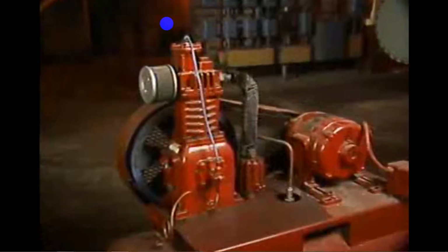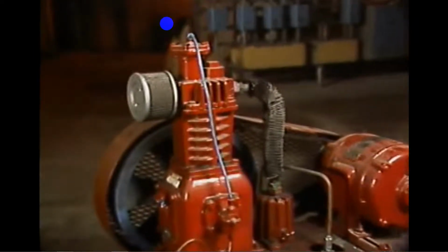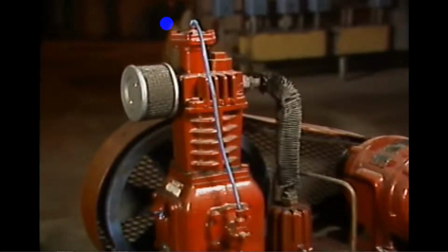Second, gases expand when they're heated, and since a compressor is designed to compress gases, this effect creates an additional force that the compressor must overcome. In other words, more work is required to compress a given amount of gas when the gas is heated. Two techniques that can be used to remove excess heat from compressors and compressed gases are air cooling and water cooling. An air-cooled compressor is easily identified by metal fins on its casing. The fins provide increased surface area, allowing more of the surrounding air to come in contact with the casing and therefore keep the compressor cooler.